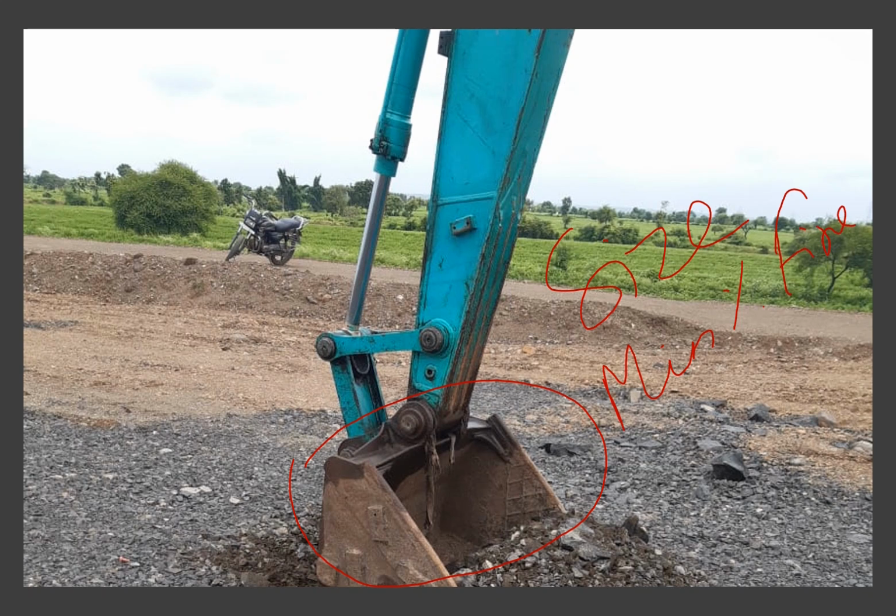So these are the things which can be done, and then the presence of voids in the rock fill embankment, to make sure that there won't be any settlement in the future because of the movement of fines into the voids.